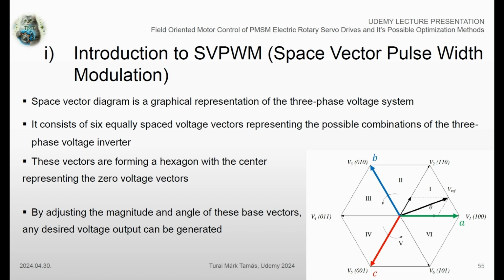This nonlinear control is only sufficient if the switching frequency of the inverter is at least 5 times greater than the time constant of the PMSM motor. In other words, the sudden jumps between the different voltage base vectors will not result in an actual rapid change in the mechanical state of the PMSM motor. If the switching frequency were too low, let's say about 10 Hz, then the motor would have an uneven jerking motion without the feeling of constant movement, which is caused by the huge torque ripples.